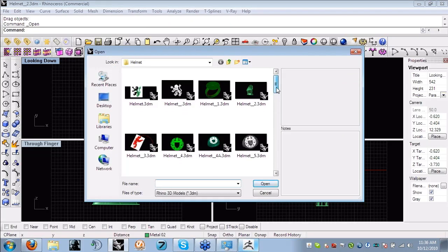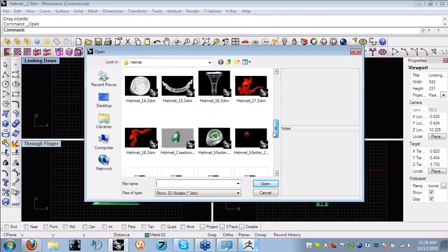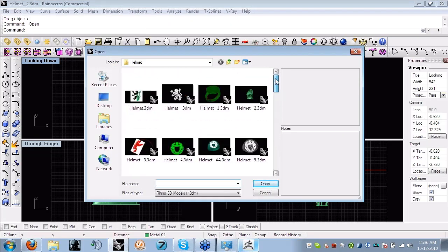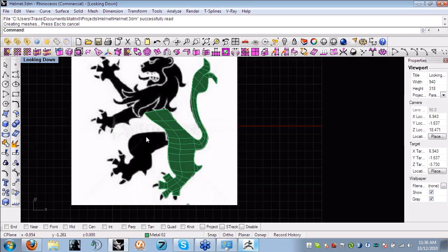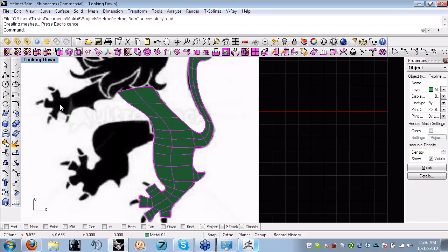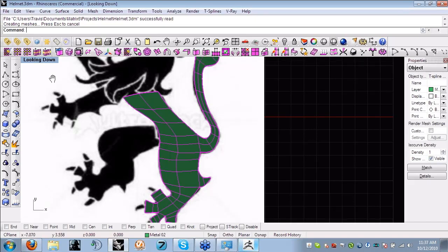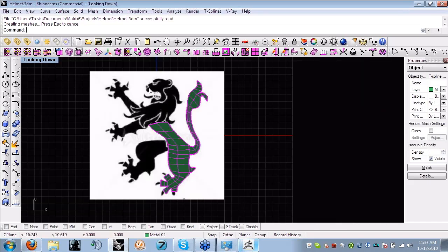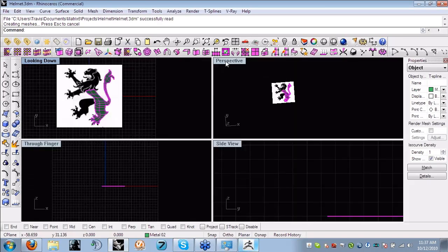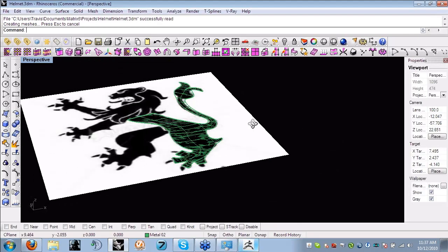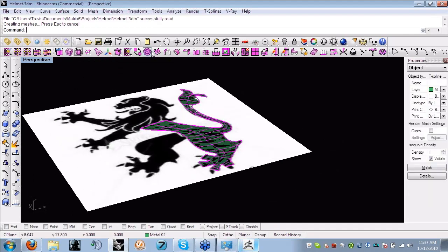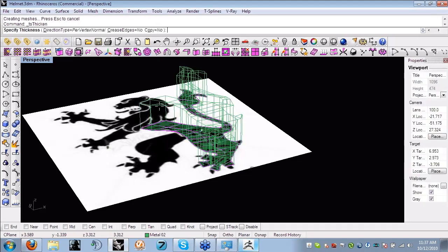Travis, one other question. You talked a lot about thickening T-splines. Could you show a simple example of how thickening works? Maybe rotating something and thickening. Sure. When I draw all these out, this is completely flat, and you can see it's just laying on top of this flat picture frame here. And then once I grab the thicken command, you can just pull it up.